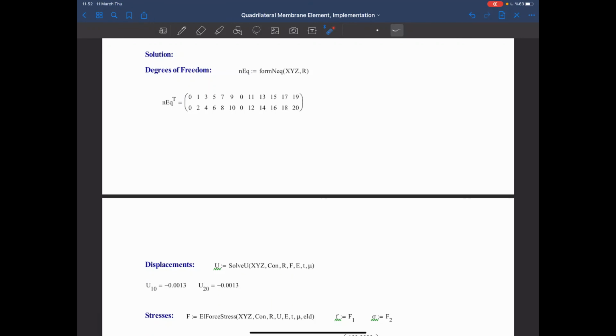If I further increase the number of elements, I expect to see a result closer to the analytical one. How many elements do I have to use? You don't know unless you try. So the first thing that you need to do in a finite element analysis is to check the mesh sensitivity of the results. As we keep increasing the number of elements, we will see that it converges to a solution.